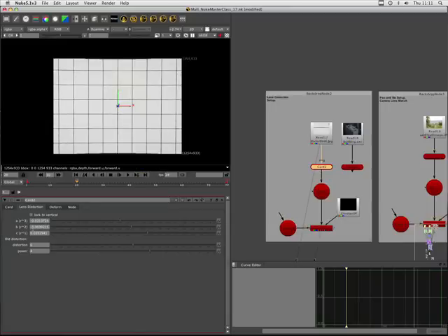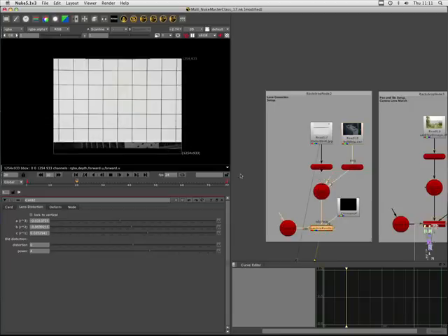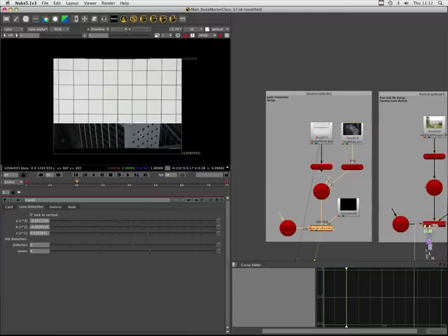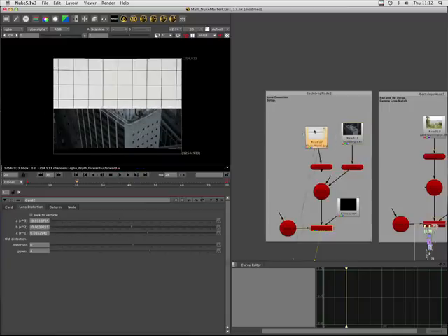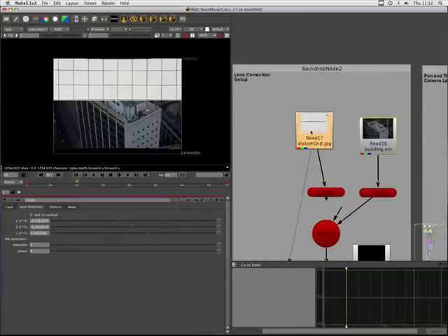And those figures here that we see can then be transferred across to other material that would have been shot with the same camera, the same lens. So although this isn't the actual image using this distortion, if I plug this in to here, you could see that this image that we looked at the beginning has now been undistorted based on the information that we got from this grid. Okay.